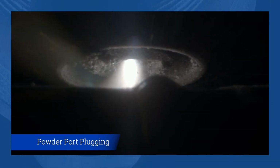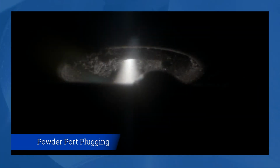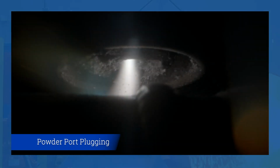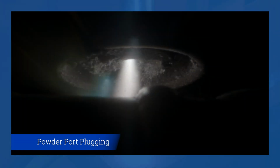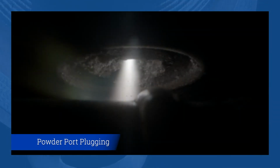Well, if you have too many fines in your powder, or you're running too low arc voltage, or you simply run too long, you can end up with one or more of these ports plugging up. And so if you have a two-port torch and you lose one of them, you're going to have drastic underfill in your weld. This is something you have to watch constantly.